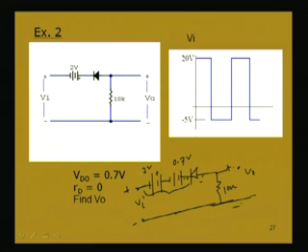In the negative half cycle, when this point is negative, this point is positive, it is forward biasing with a plus 5 volt. So, the potential here is plus 5 volt, this potential is 2.7, that is, the end point is having plus minus 2.7. So, here this point is having a higher potential, 5 volt, than this point, it will be conducting. So, in a negative half cycle, what will be this voltage?